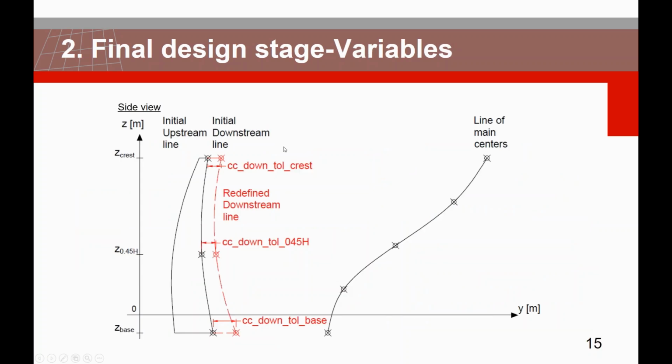And right now, let's take a closer look at how we can redefine these three parts that I mentioned. First of all, here we can see how we can thicken the entire crown cantilever section. This dashed red line shows how we can thicken the crown cantilever section. And by making it even thicker, the entire dam becomes more resistant against the hydrostatic pressure, for example.